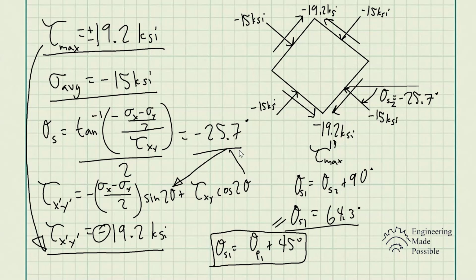And so this is how you solve for the principal stresses as well as the maximum shear stress developed at a particular angle for both of the cases. It's very important for design to make sure we're accounting for the maximum shear stress developed as well as the maximum normal stresses, or the principal stresses, such that the object won't fail. And knowing the angles along which these maximum normal stresses as well as the shear stresses develop matters, because sometimes objects may fail along that same direction, based on the angle where the maximum shear stress is developed or where the principal stresses are developed. So that's one fun fact there. It's pretty interesting.